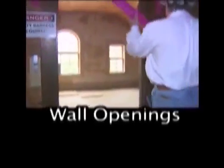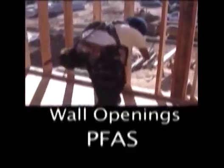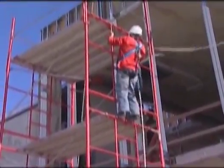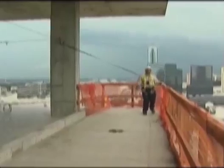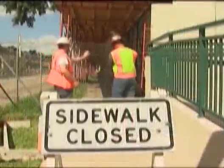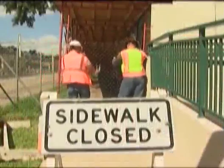Wall openings should be protected by using guardrail, safety net, or PFAS. To protect employees from falling objects, employers must ensure employees wear hard hats and have properly designed toe boards, screens, or a guardrail system. As an alternative, the employer can erect a canopy or barricade the area where objects could fall.